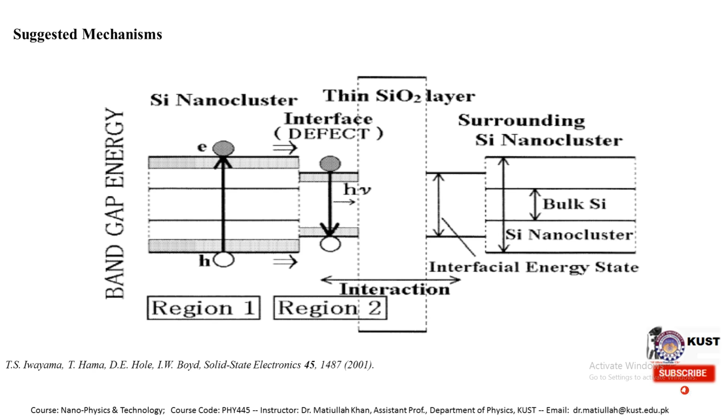So this is the suggested mechanism for the electron transfer between the bands in these silicon nanoclusters, and how the electron hole pairs are created. Normally, when a photon of suitable energy falls on the valence band, the electron is migrated toward the conduction band, leaving behind a hole. In a silicon nanocluster this would happen when an interface is created between a semiconductor with high band gap and a semiconductor with lower band gap.